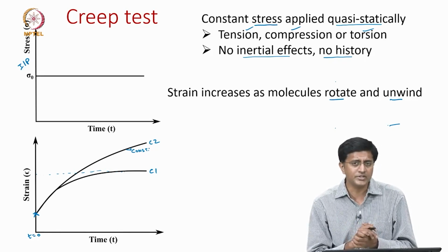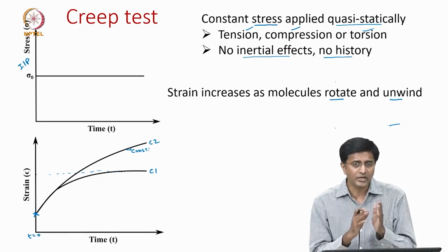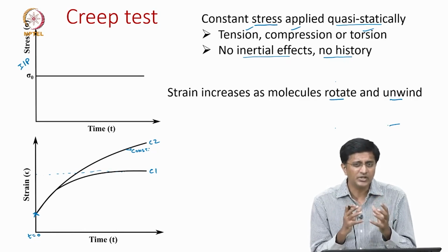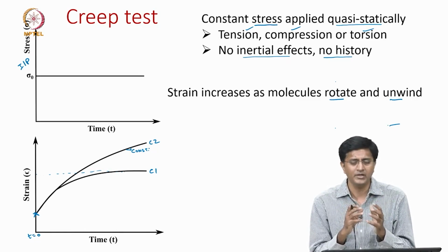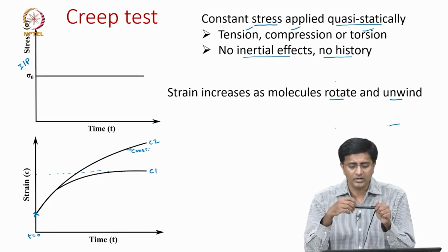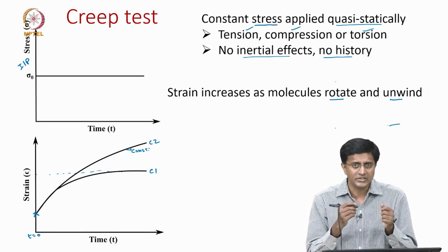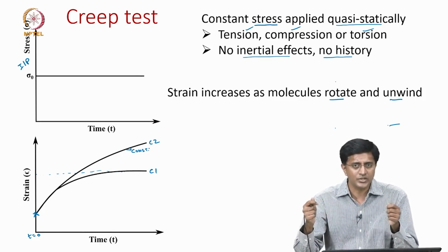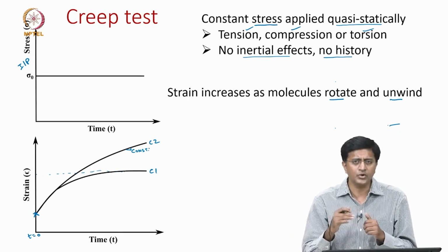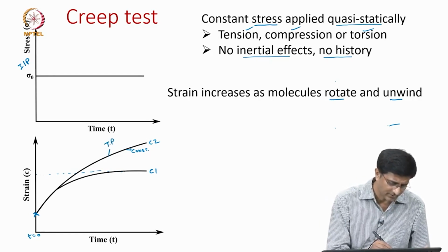So, if you think carefully, we said thermoplastics, especially if you give more time, these polymer chains slide against each other, which means it is more like a fluid, right. If we think about it more like a fluid and we are saying there is continuous load, how do we expect that strain to be? We expect that strain to keep on increasing. There is no reason for the strain to stop or to reach a constant value. So, this should be our thermoplast.